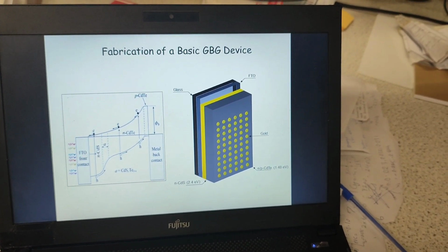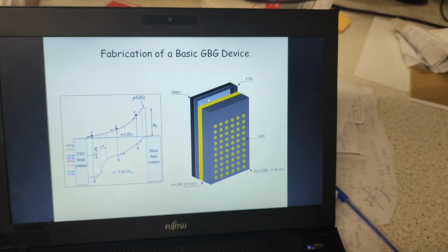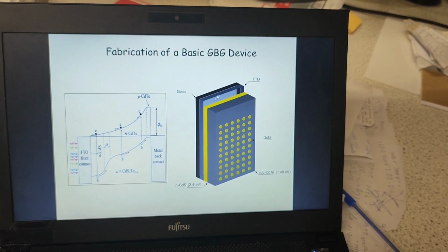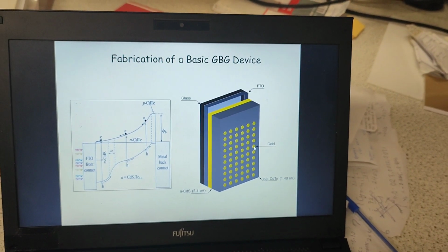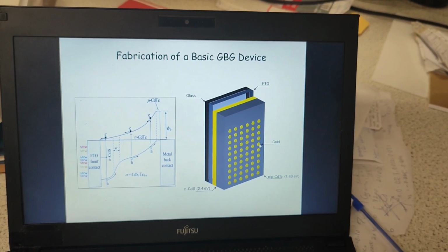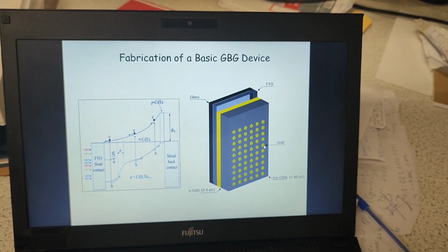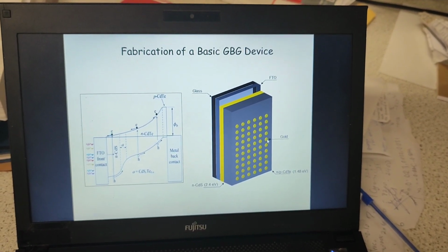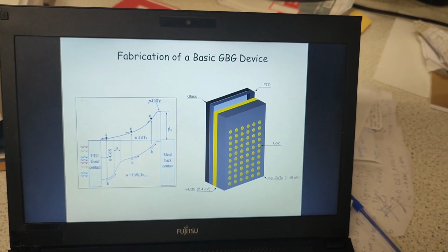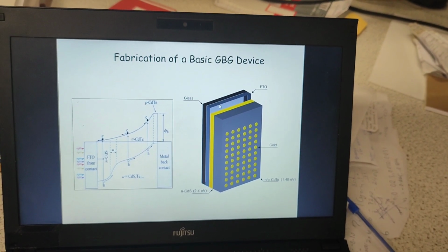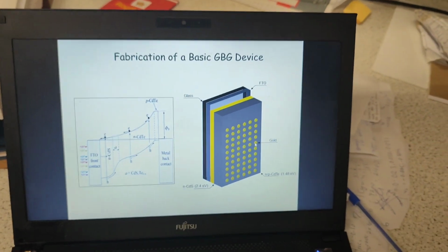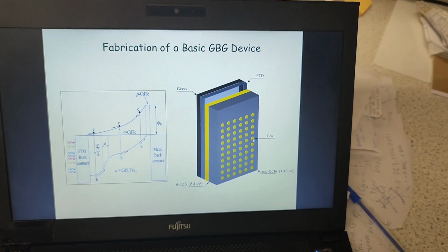We can see that there are mainly two conductive contacts. One is the one at the beginning, the TCO or transparent conductive oxide, and there is another conductor which is the back contact, the metal contact, which can be of gold, aluminium, silver or indium, depending on what the device requires. We call the contact over here the front contact, and the other contact is called the back contact.